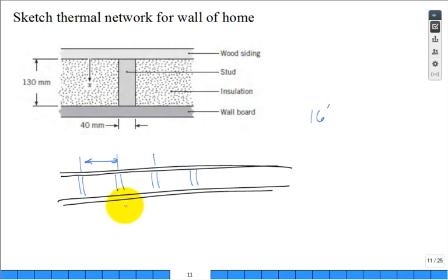But anyway, if you wanted to analyze the flow of heat through the wall of a house, forget the windows, forget the doors, just look at the wall. This is easy now. And it's the same thing for the ceiling. The ceiling has those rafters going across, okay, and they're frequently spaced at 16 inches or a little wider. Most of it's 16 inch. Okay. So what you would do is you can get a section of it and analyze the section.